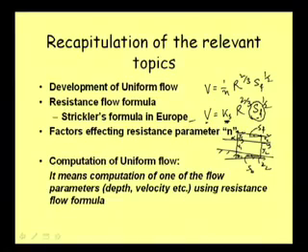But in uniform flow, this Sf and this Sb, that is the friction slope and the bed slope, remain the same, because our depth is the same in that portion where we are considering uniform flow. In that channel reach, the depth is constant, then velocity is the same, and as such our energy and everything remains the same.